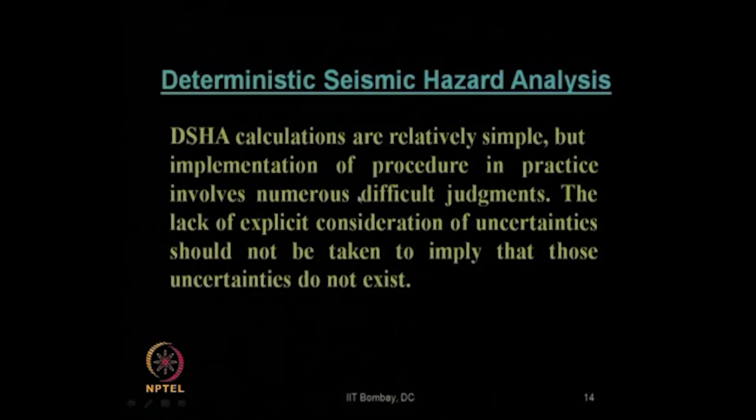implementation of the procedure in practice involves numerous difficult judgments, like whether that maximum earthquake really occurs or not, whether the minimum distance chosen is justified or not, and many other certainties and uncertainties. The lack of explicit consideration of uncertainties should not be taken to imply that those uncertainties do not exist. Actually, all the uncertainties exist, but we always consider the worst case scenario, or the critical scenario, for the deterministic